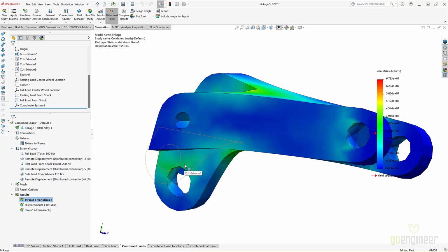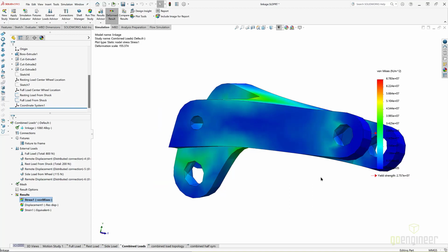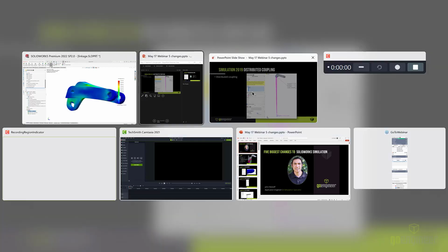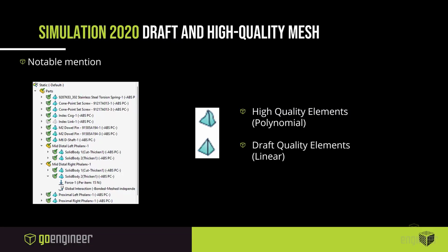Furthermore, this is also made with a pretty coarse mesh. So if we were expecting hotspot concentrations, then this is probably the model we would get it. And luckily, having that new linear distributed load is helping us eliminate those concentrations because we're no longer rigidly held to those nodes. The weight factor isn't rigid anymore. There's now some dissipation from that with respect to how our setup is made.